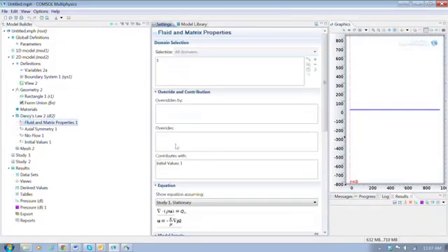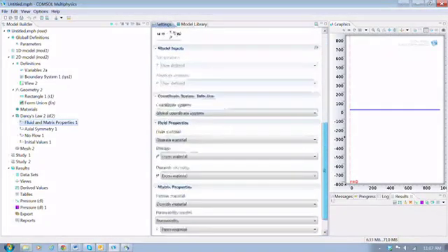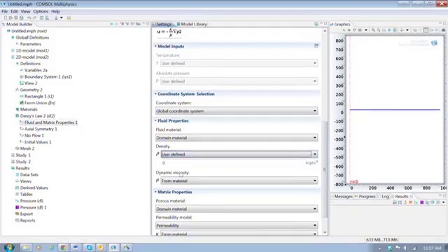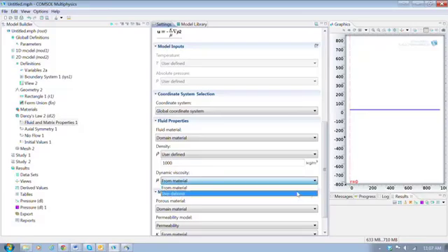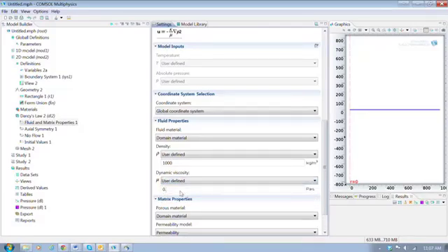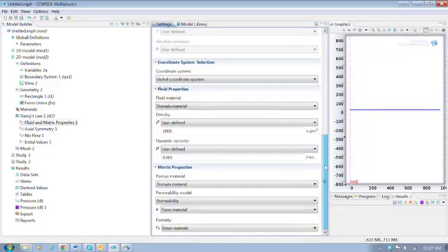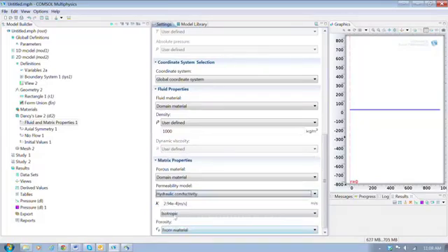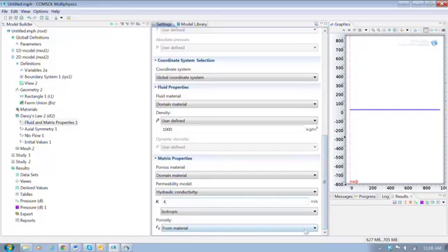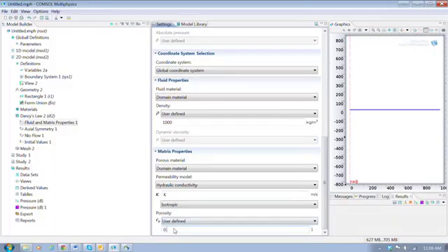Okay, so we go to Darcy's law, and this will be the same routine that we've done before. We need to give the fluid properties, and they'll be the same properties that we used previously. So we'll put in 1,000 kilograms per cubic meter for the density and 0.001 Pascal seconds for the dynamic viscosity. And the hydraulic conductivity, we've imported that in the file, and we'll call it K. And the user-defined porosity that we'll give it is just 0.1.